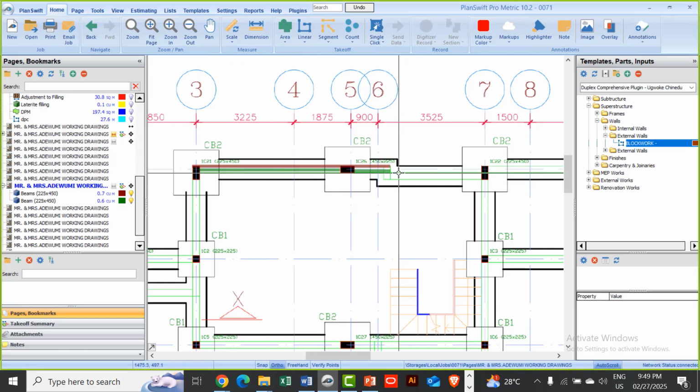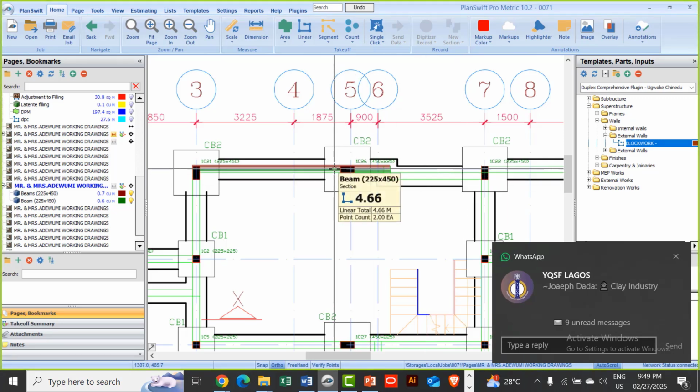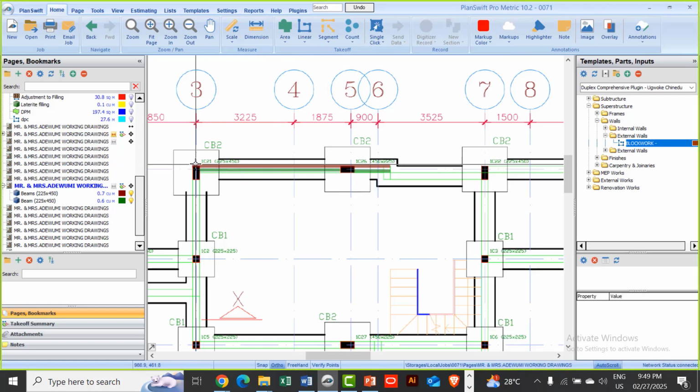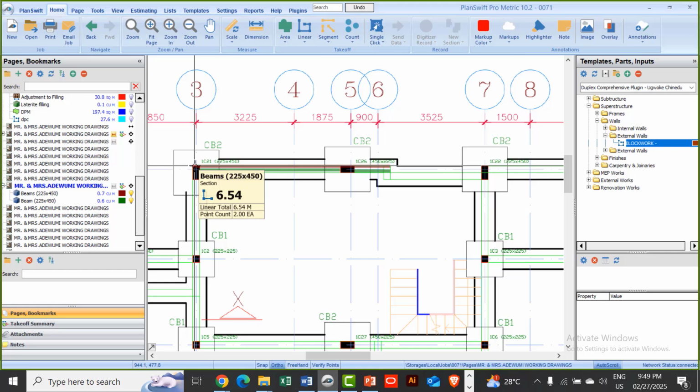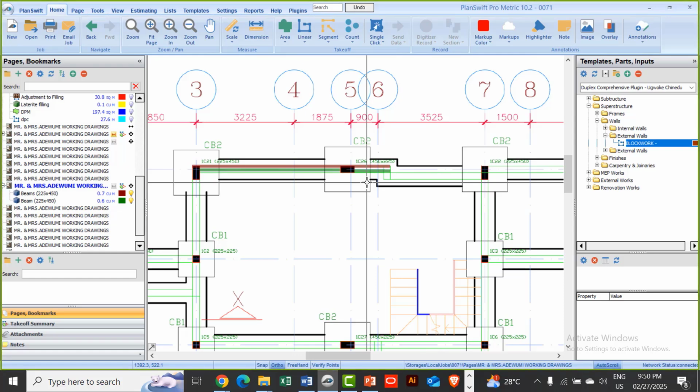I don't want to know whether there's column or no column. But if in your firm they say measure in between the columns, measure in between the columns like I've directed you. But for me, I will advise every one of us on this call, measure across the column. I believe that answers your question, QS Clinton.